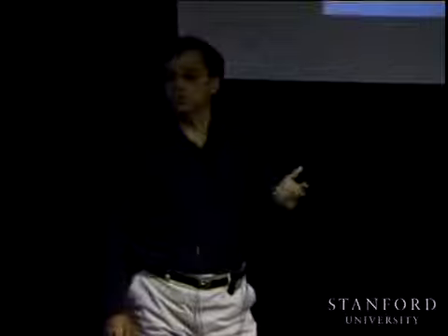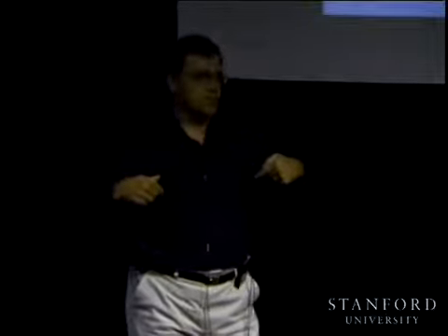And the other major problem is that we have discontinuity problems here. If we are planning in Cartesian space, we have our nice straight line that we are following in Cartesian space. We convert to joint space, and it might turn out that it is impossible to do that in joint space.